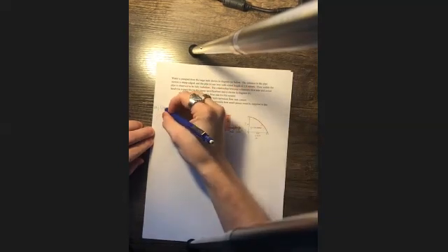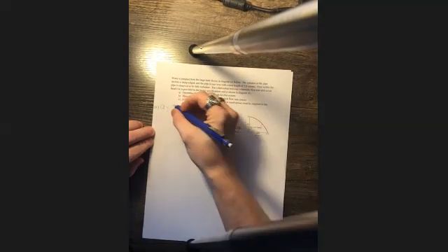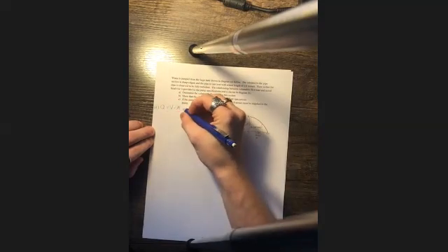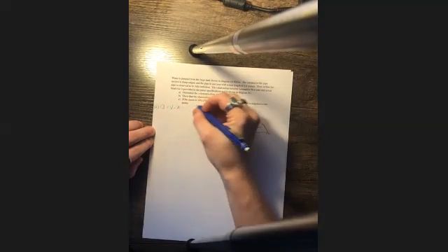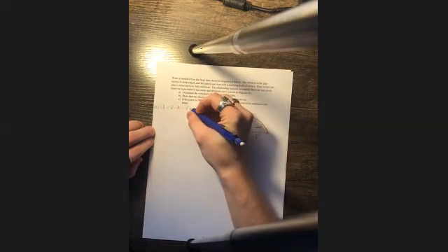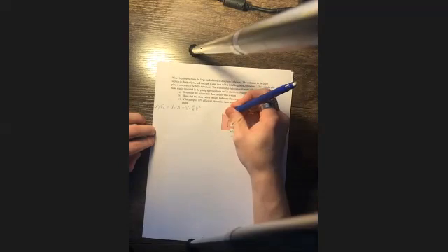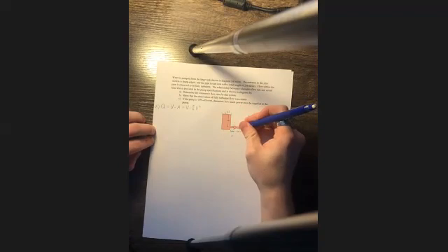Volumetric flow rate, Q, equals velocity times area. Area is pi over 4, pipe diameter squared. And velocity here, let's pick 2 points so we can do the Bernoulli's. Point 1 is at the top of the container.